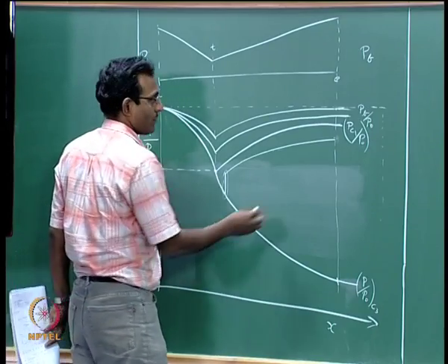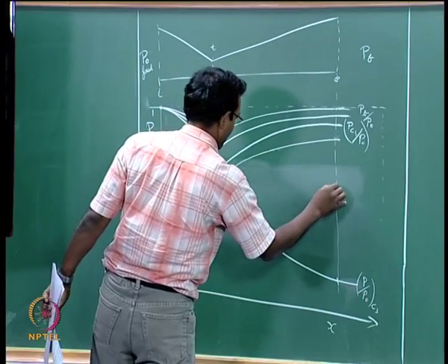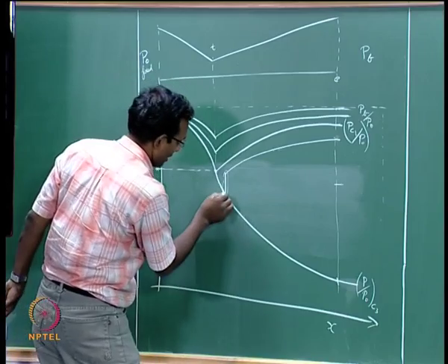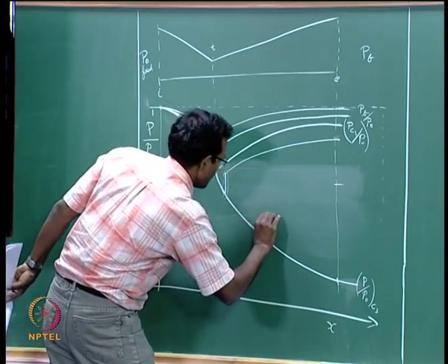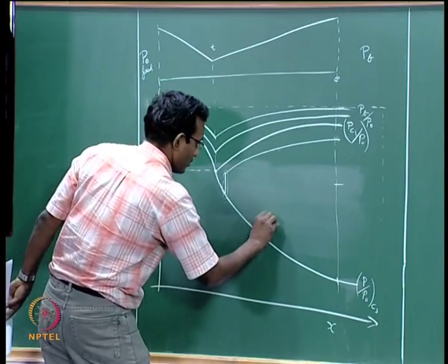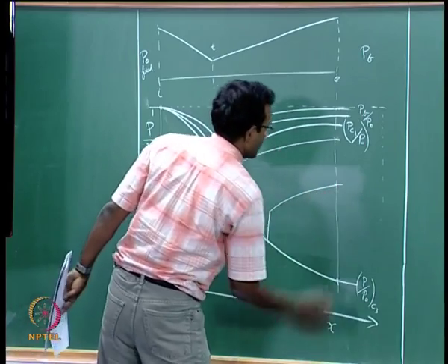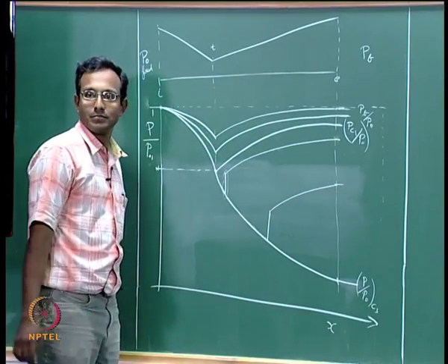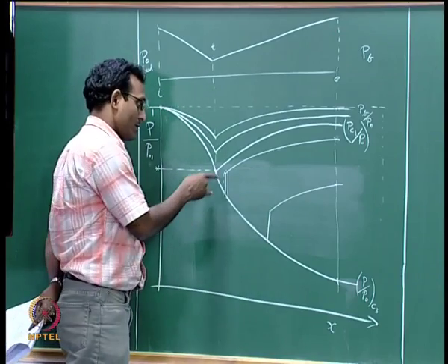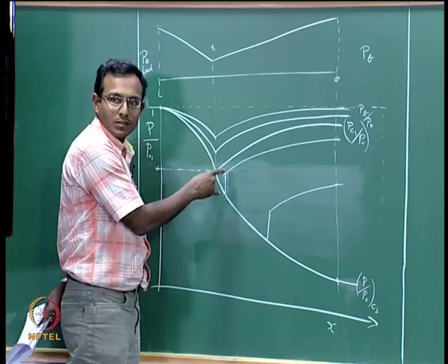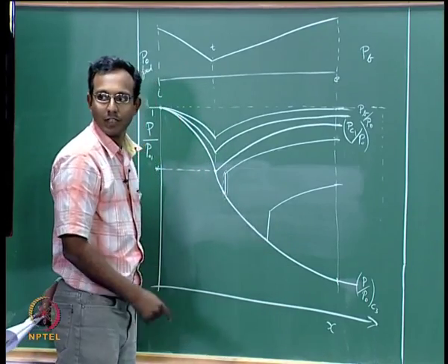Okay. Now if I go for even lower pressure than this value, let us say somewhere in here, then that will take the supersonic path for even longer, jump up to a subsonic solution, and from here it is going to reach that value, something like that. It is going to pick some such solution. You should know that the P2 by P1 jump is going to be higher and higher as it goes down here. Okay, that is also true.